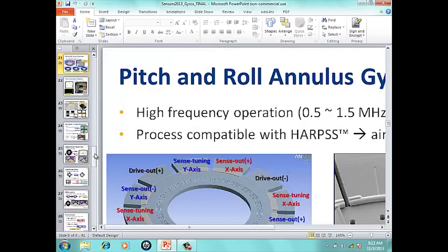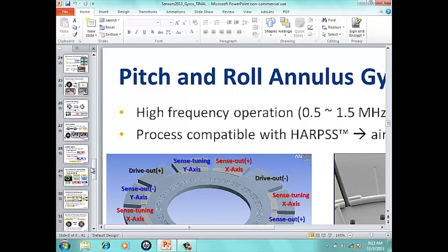Having differences between the Q of mode 1 and mode 2, you can see that as part of the energy in one mode being dissipated faster than the energy in the second mode. So effectively, you could say that some of the energy of the mode with higher Q is being leaked into your second mode. And that leads to this damping coupling, that D1-2 term,